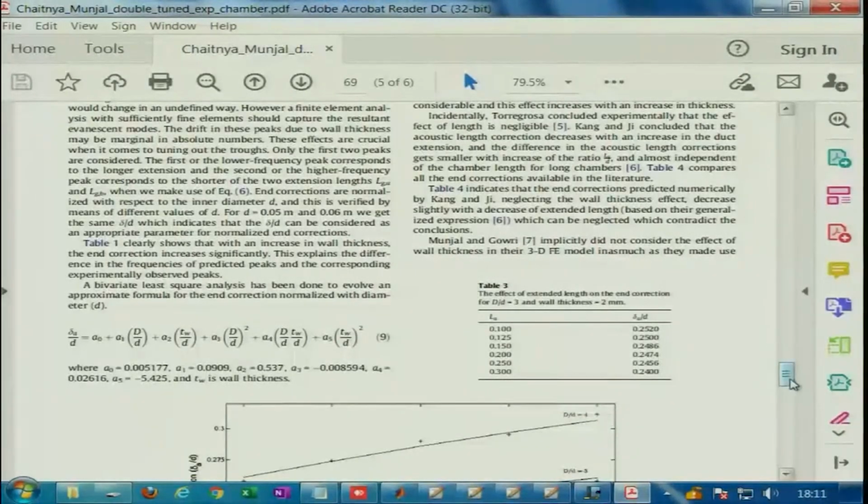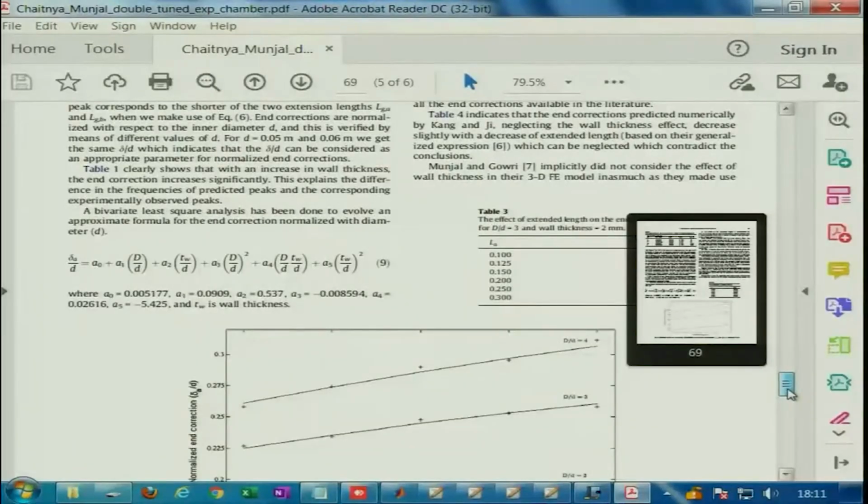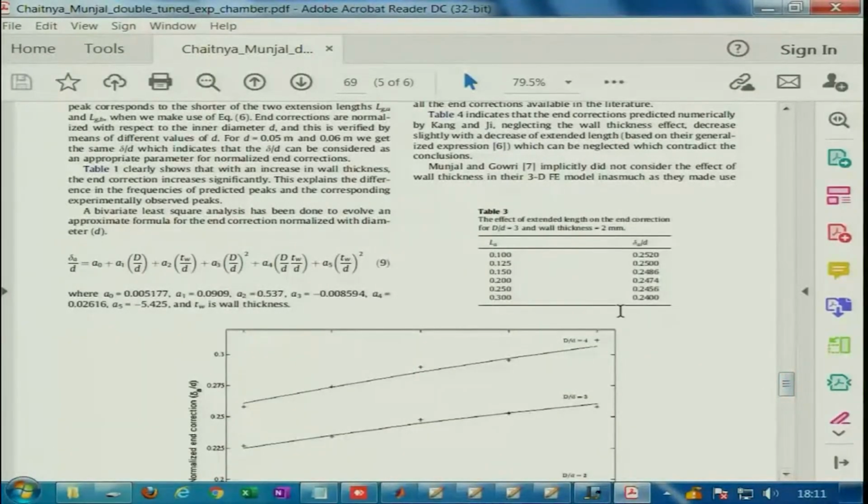So, this expression can also be evaluated using our analytical mode matching code, or using finite element simulations, or perhaps using experiments, if you can get those many muffler models fabricated. So, people rely on simulations to find these empirical relationships within a certain parameter range, for example, expansion ratio varying from 2 to 6 or 7, and the pipe diameter typically varying from 30 mm to 60 mm. Wall thickness is from 1 mm to about 5 mm. You can also set 0 mm.